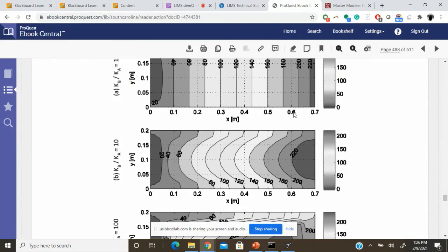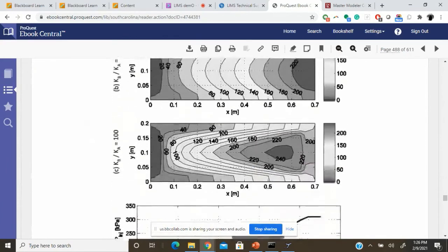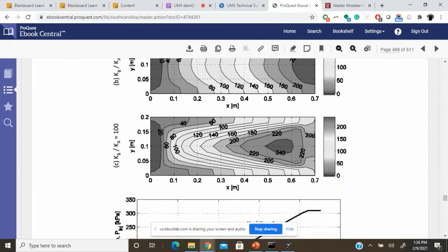So in this case, you will see the race tracking effects, and you will see how the resin is moving through the fiber fabric preform. When there is a vast difference in the nature of the preform itself, you would observe sharp trends between zones A and B with the flow of the resin itself.